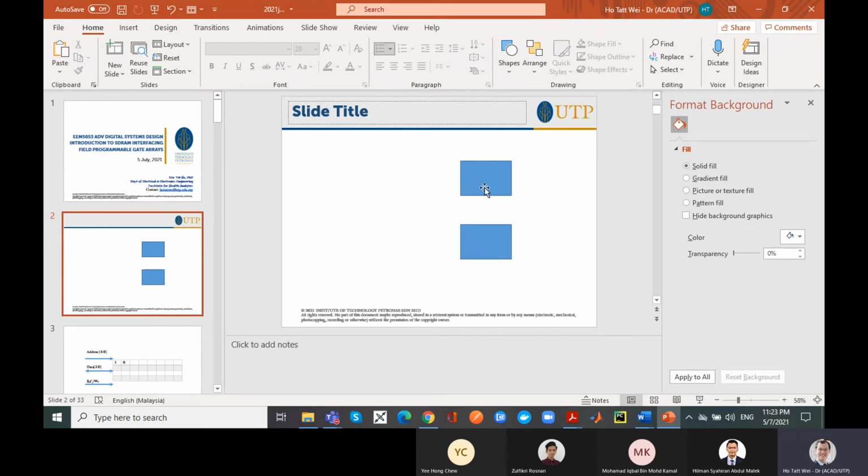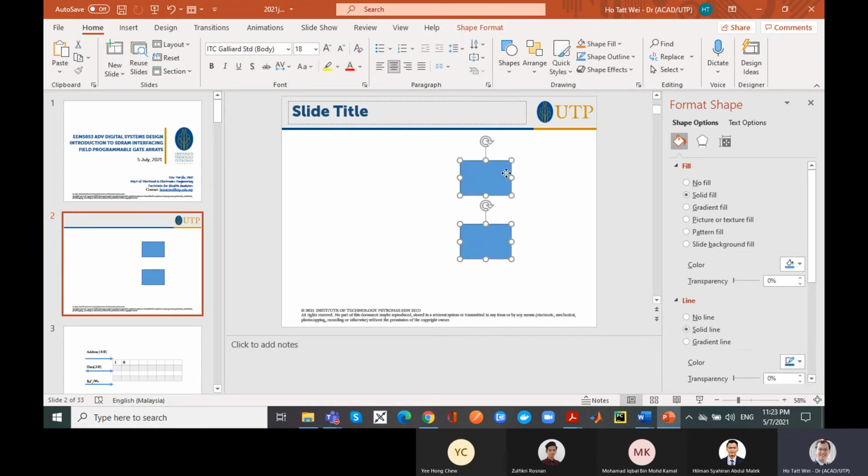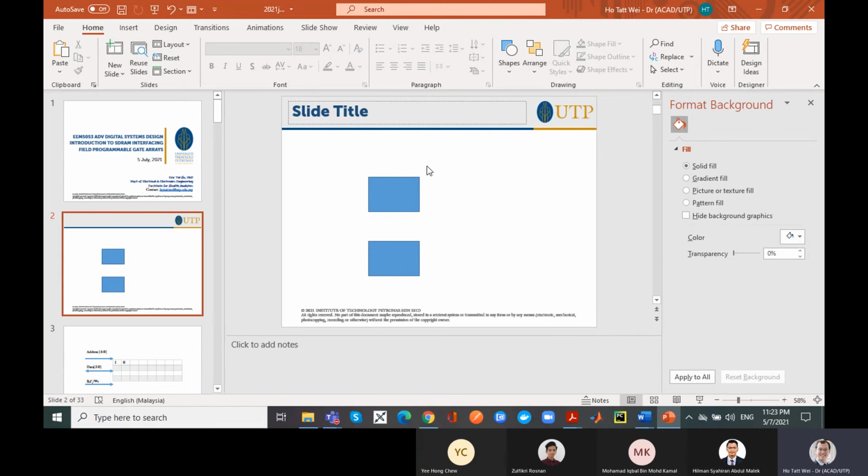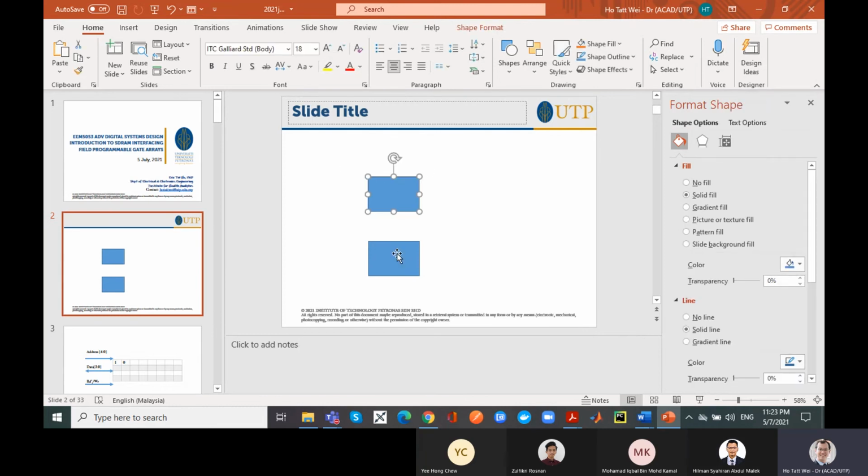But what I want you to understand is you were taught a very specific way to do state machine. That is, you got previous state and next state, right? From digital electronics. I want you to break out of that and understand this. These square boxes are flip-flops. Now I've got only 2 flip-flops. And please forget your T flip-flop, your JK flip-flop, or throw all away. In the real world, everybody just uses D flip-flop. The main reason is because with a D flip-flop, whatever is at the input is sent at the output. And now you will understand why. A JK flip-flop can be implemented with a D flip-flop with some logic.